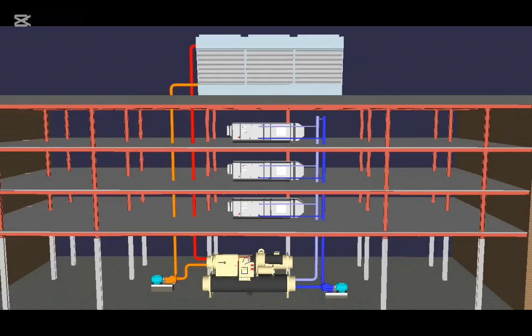You might even have a number of separate chilled water systems. You could have a system which deals with critical loads, so it's generator fed, and it supplies only the server rooms because they need cooling 24/7, and you'll have this common centralized system which handles the space temperature within the floors.